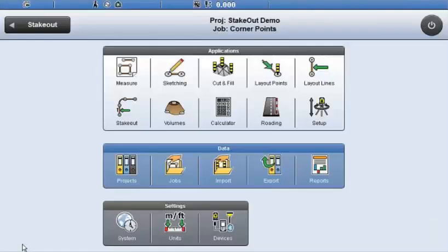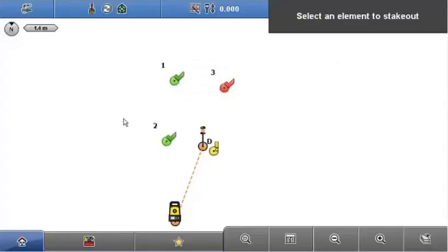Okay, so you can see I've staked points at different tolerance levels with different guidance, at different distances from the reference data, to display the results. I've also shown the arrow view along with the 2.5D bullseye point guidance. The arrow view and the 2.5D guidance were newly introduced for version 1.5, based on feedback from earlier versions saying that stakeout could be a little bit more straightforward. The feedback on these features has been universally good, and it's a massive improvement. Ultimately, it allows customers to stake out more points in less time.